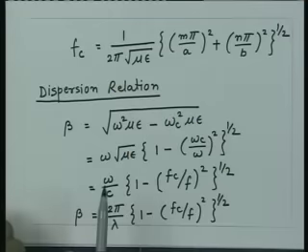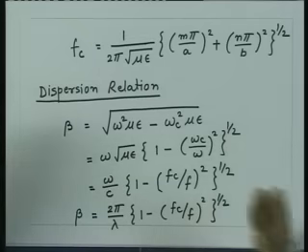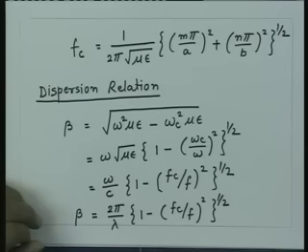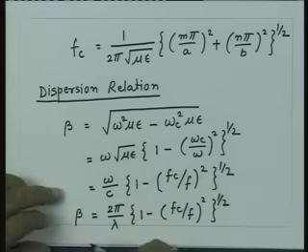That means, this quantity beta, whatever we have here for this particular mode, this quantity is 2 pi divided by lambda, which I am going to measure on that waveguide. This lambda is certainly not the same lambda which intrinsically the wave has in an unbound medium. That means, if I know the properties of the medium mu and epsilon, and if I imagine this medium to be infinite, then I get a wavelength called lambda, which is the velocity of light divided by the frequency.